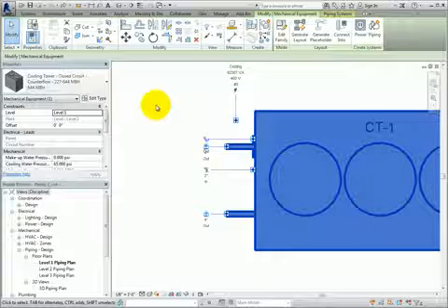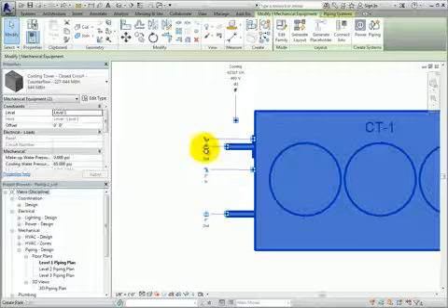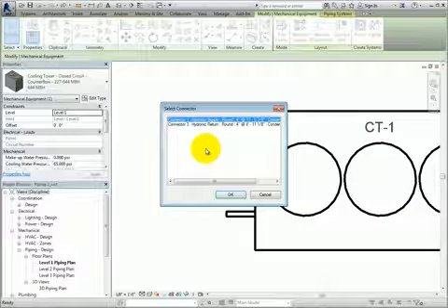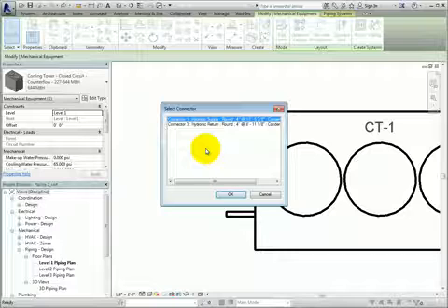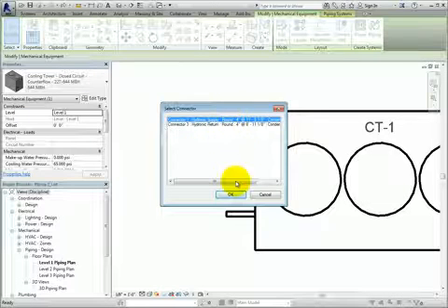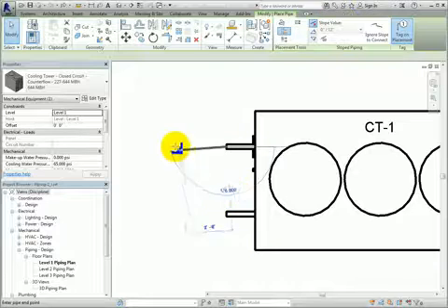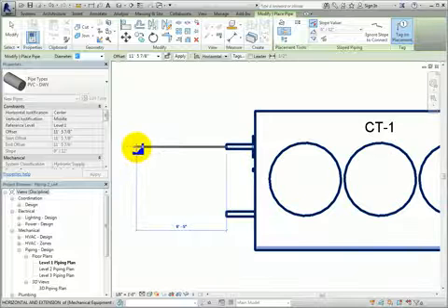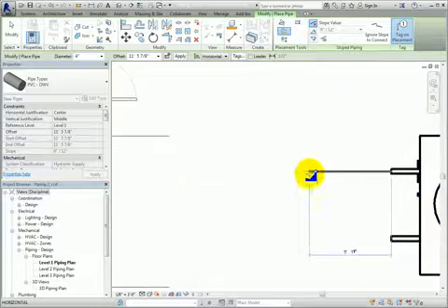I will click on the top hydronic icon. When I do, a Select Connector dialog appears. This is because there are two connectors at the same location in Plan View, but they are at different elevations. I will select the hydronic supply connector and then click OK. Once I do, the pipe tool is active and the starting point of the pipe segment has already been placed at the connector I just selected.